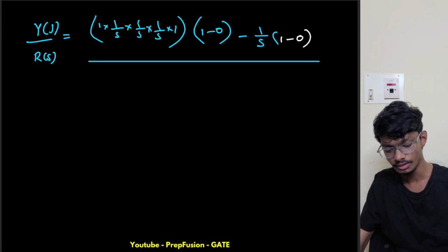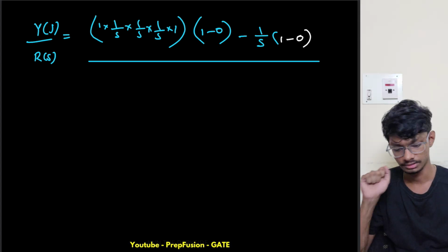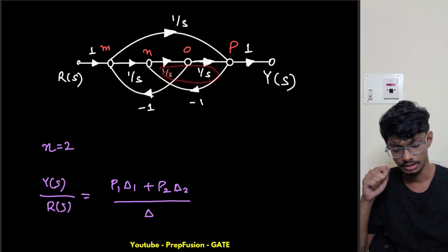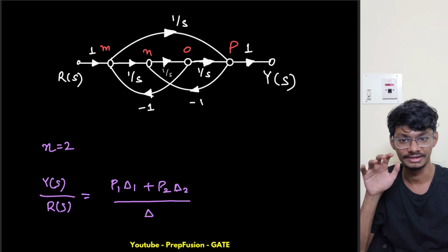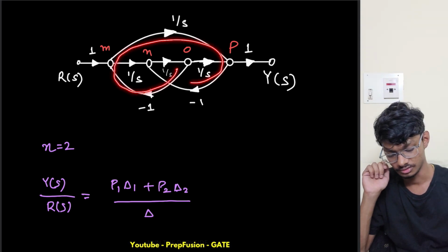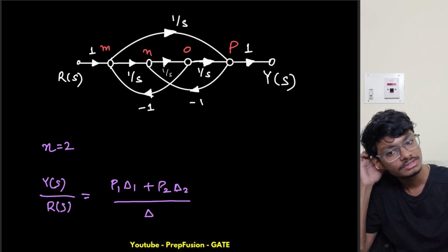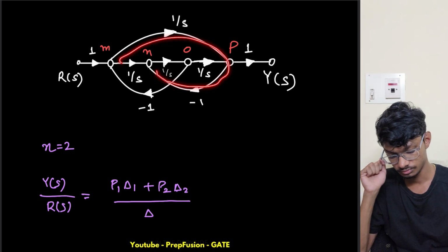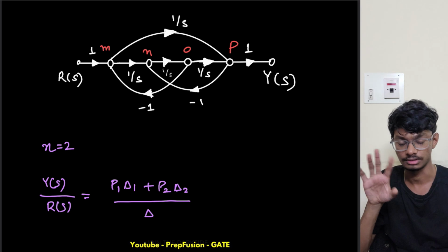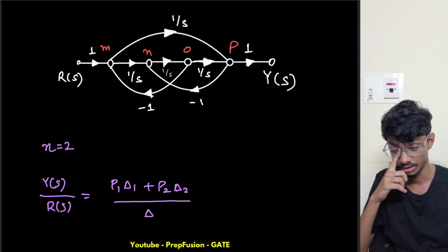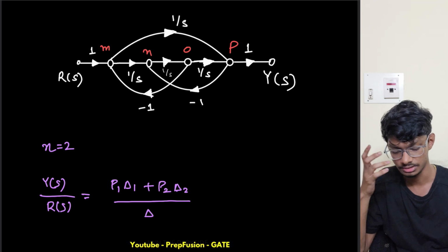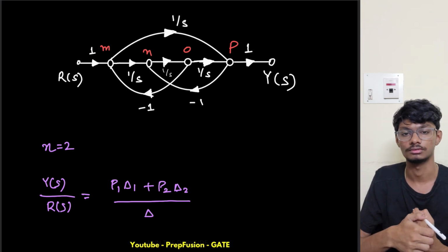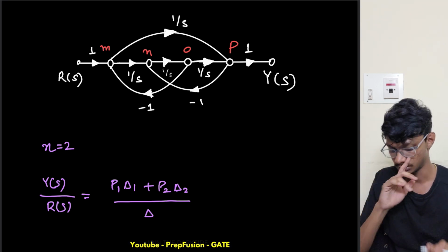Now let's find the determinant of the SFG. This is one loop and this is one loop. I revealed to you that one loop is a bit hidden. This is the other loop. Sometimes you have to be very careful about how many loops there are. So this is another loop, and they are not repeating nodes, but all of them are touching each other. They have common nodes. So the second term, two non-touching loops, will be 0, but there are 3 individual loops.